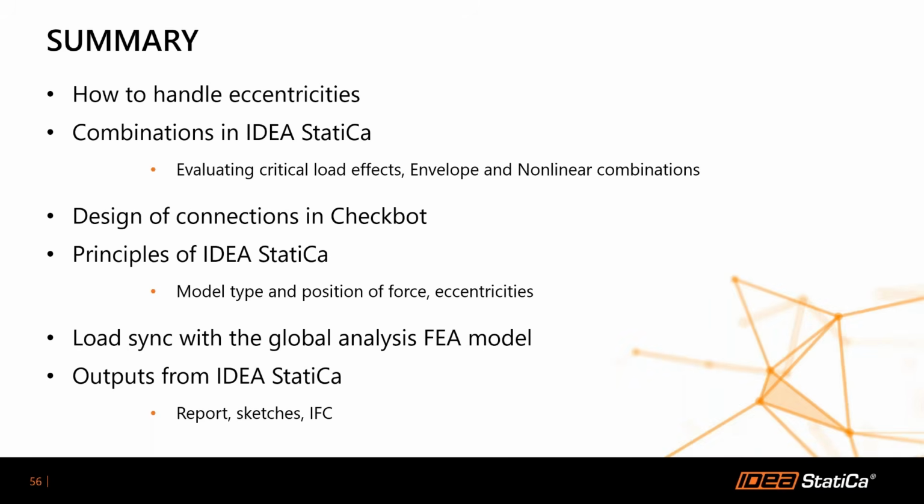Another thing you can do is utilize the parametric templates functionality, which again helps the automation. Then we touched upon the principles of designing in IDEA StatiCa: the model type, the position of shear force, and again the eccentricities and loads in equilibrium. It's always important to have that on and keep the forces in equilibrium. Then Łukasz showed us how to use this sync functionality to synchronize the Checkbot with the global analysis FEA model.